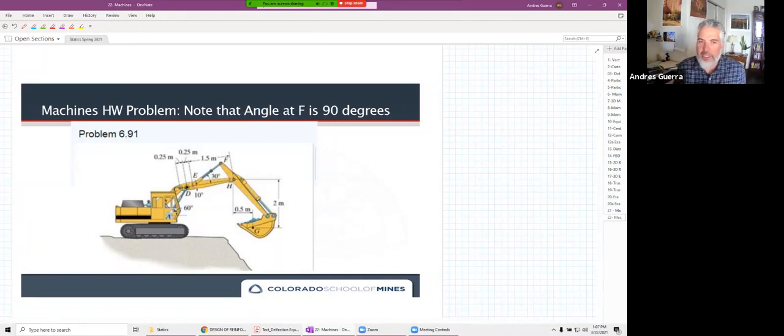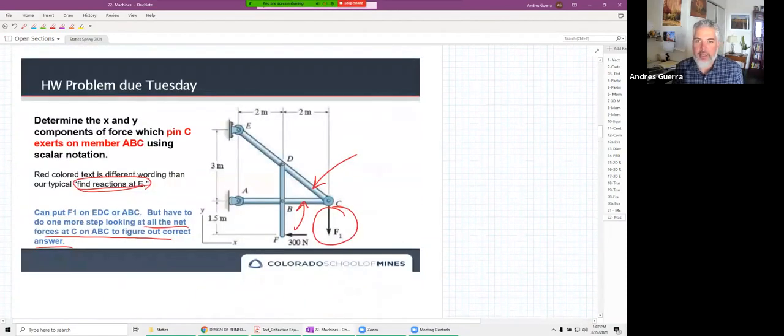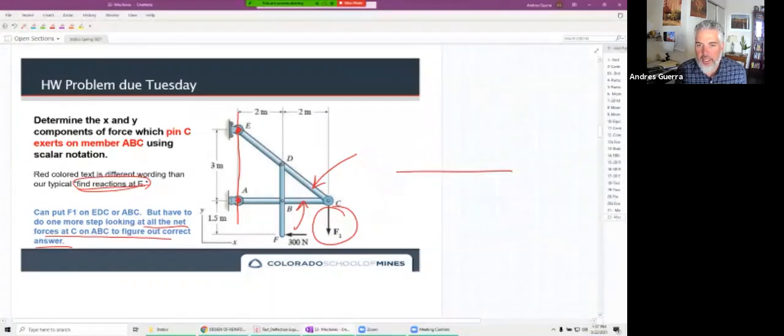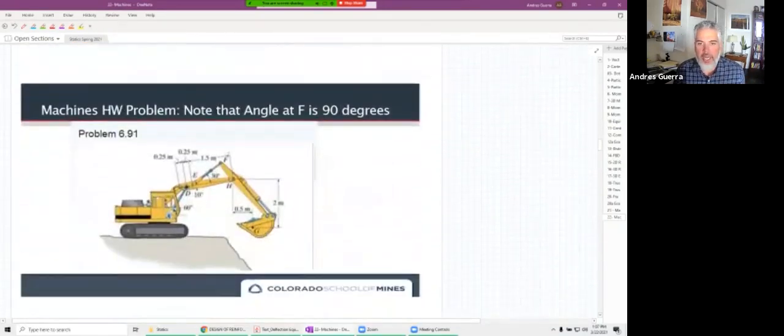There's no particular order to go through those in, but a lot of times the supports are typically in a vertical line or in a horizontal line. Because they're in that vertical line, we can solve for more unknowns. We can have 4 unknowns and still solve for things because 3 of those unknowns will cancel out when we do moment. So the whole thing is definitely a good option to look at, but not all the time.